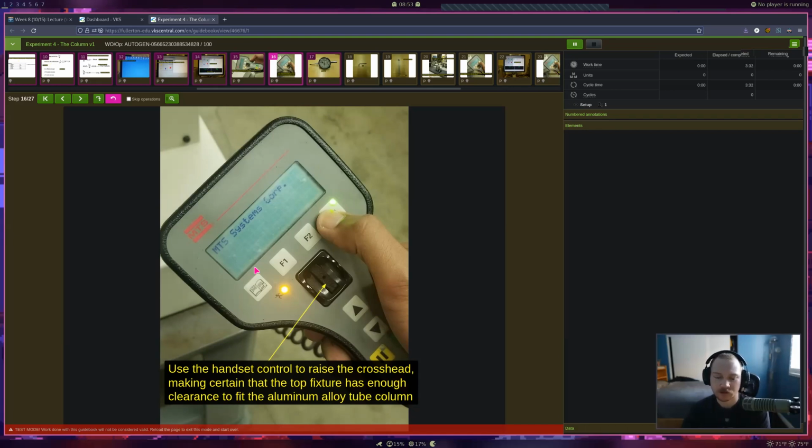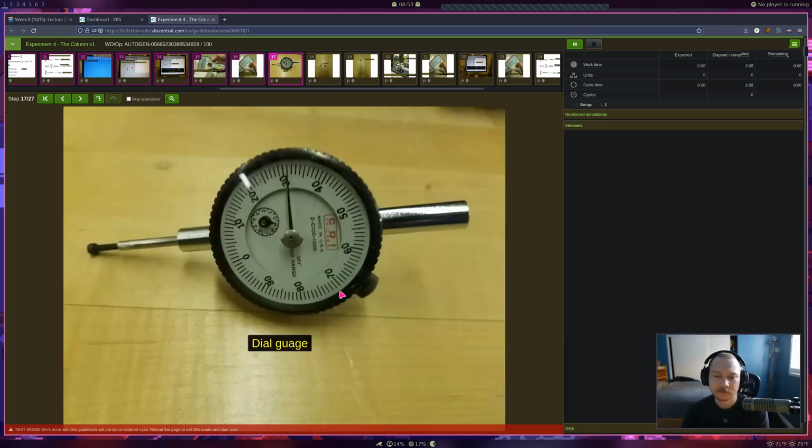So basically we're going to use this thumb wheel to continually apply load in set intervals. This dial gauge, we use this to measure the deflection that we have, so the horizontal deflection. But we actually typically don't use this, because for the most part we don't do this part of the lab, measuring the deflection, because it's so inconsistent. Really, the data is just not good.